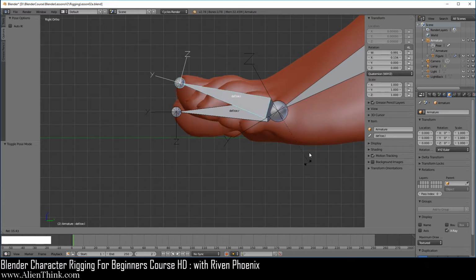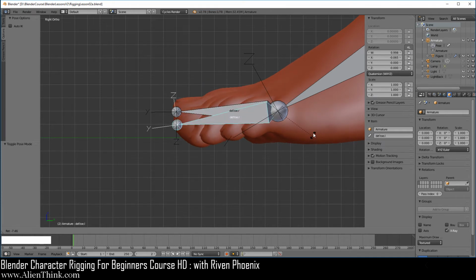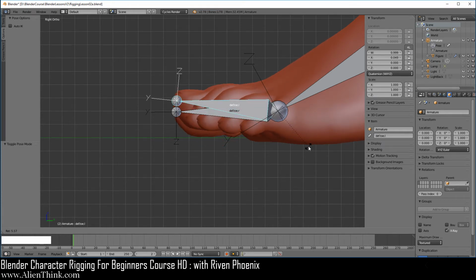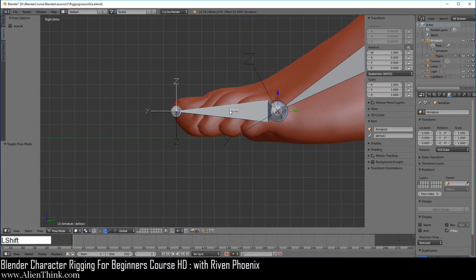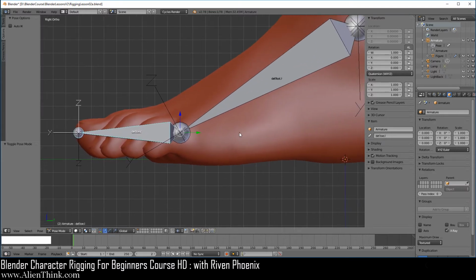It's just based on the view. But because the way the bones are aligned, it still works. So we can use this concept to quickly check these bones, how they're rotating, because they're aligned this way. Okay, right click to cancel. So this bone is now set up correctly.